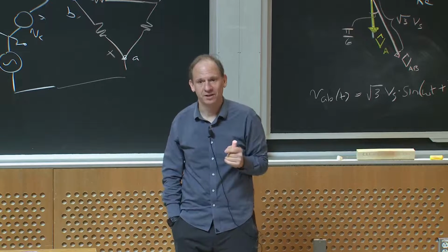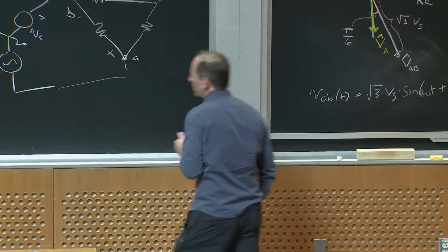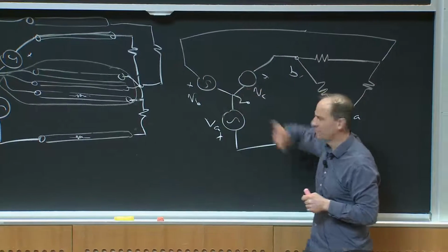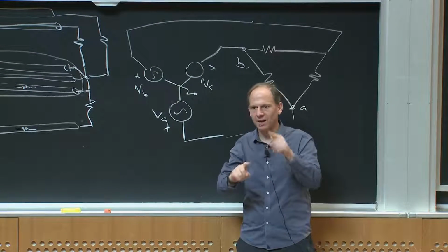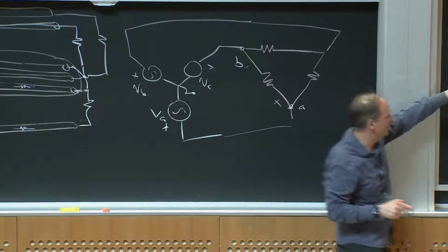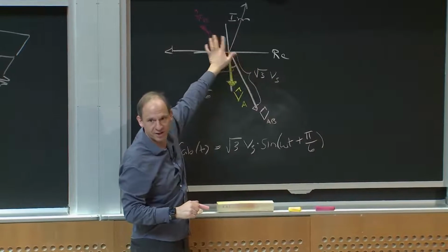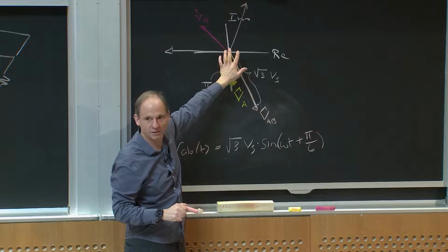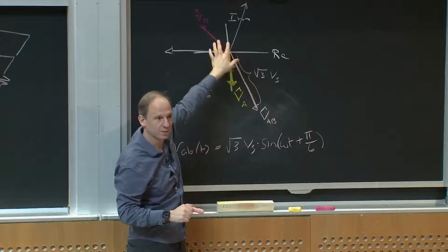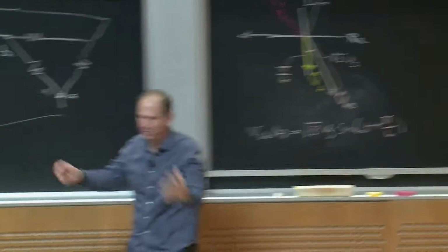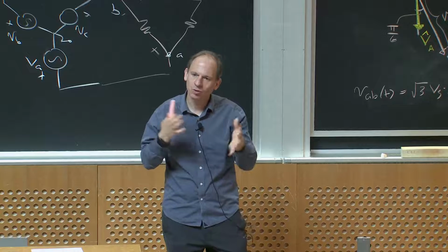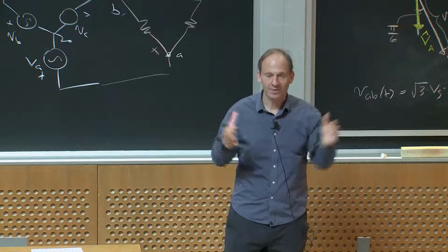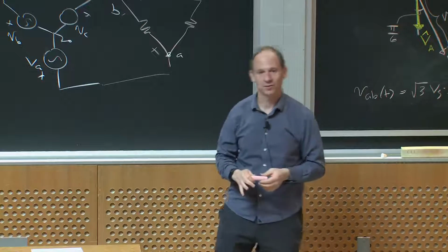But here's the other piece of it. By adding up, I could take transformers. If I had this three-phase set, I could take transformers, take a piece of this voltage, a piece of this voltage, and a piece of this voltage. And if I do that in a balanced way, I can actually create three-phase sets with any arbitrary phase shift that I want. Okay? And that turns out to be handy for some kinds of converters you might want to build, because we can do things like we talked about, harmonic cancellation or ripple cancellation with interleaving. I have a natural way to generate phase-shifted sets of signals if I have a balanced three-phase set, and I can generate other balanced three-phase sets.